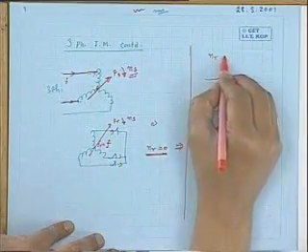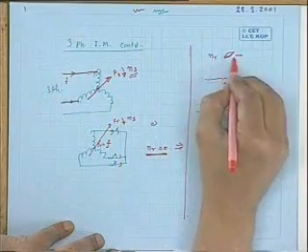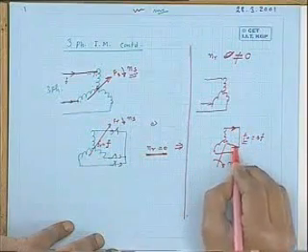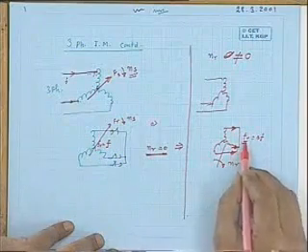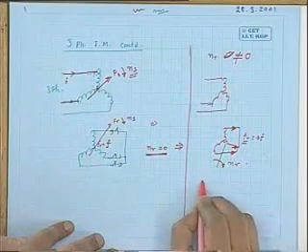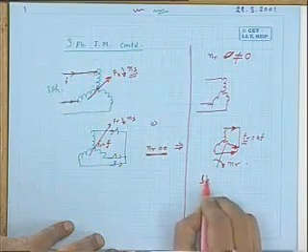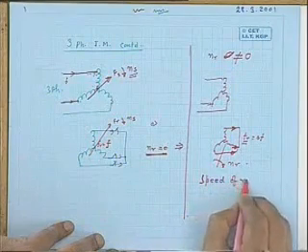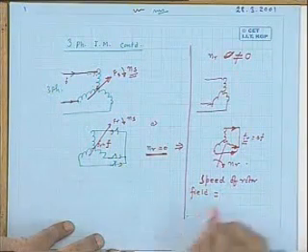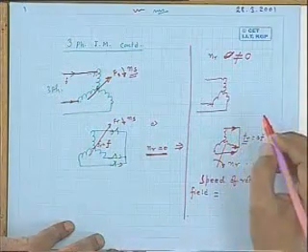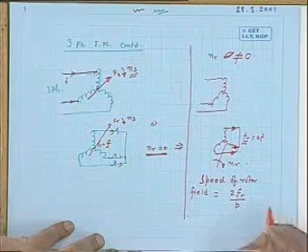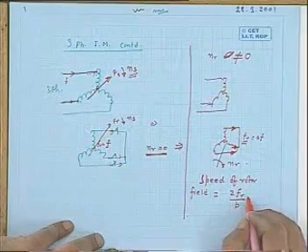In this case, where nr is finite, nr not equal to 0, the rotor will have currents of frequency Fr, balanced three-phase current it will be, and its speed, the speed of the rotor field, will be how much? N equal to 2f by P. So 2Fr by P, the mechanical speed I am calculating, 2Fr by P. This will be the speed of the rotor field.